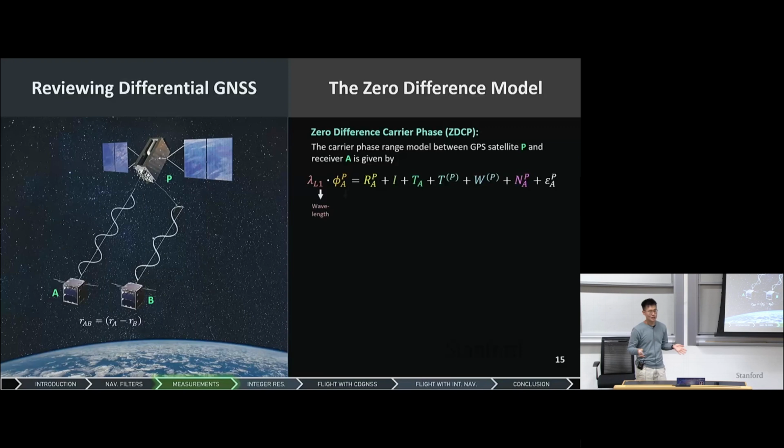And there's been a textbook way of how we model carrier phase. This is kind of the agreed upon in literature. Most people adopt this model. So your carrier phase measurement expressed in meters. So this is your actual phase in radians multiplied by the wavelength. So this is in meters. It is basically a measurement comprising your true range.